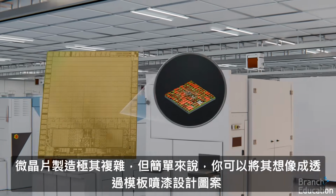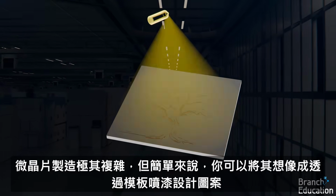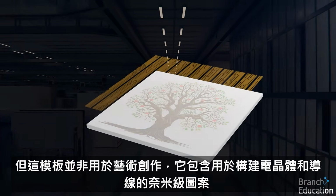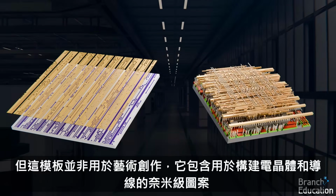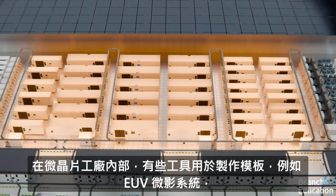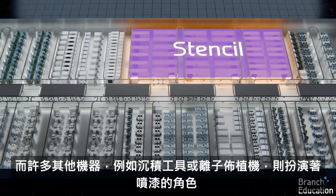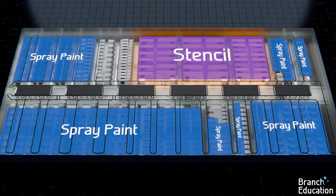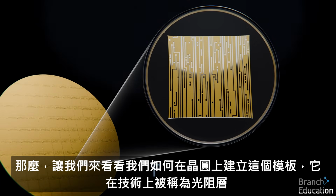Microchip manufacturing is incredibly complicated, but a simple way to think about it is that it's kind of like spray painting a design through a stencil, but instead of art, this stencil contains the nanoscopic patterns used to build the transistors and wires. Inside the microchip factory, some tools are used to build a stencil, such as the EUV lithography system, and many of the other machines, such as the deposition tools or ion implanters, are the spray paint. So let's take a look at how we build a stencil on the wafer, which is technically called a photoresist